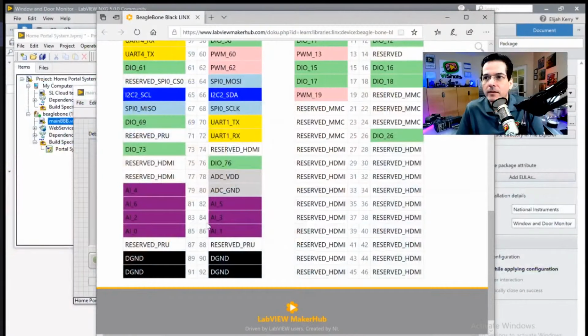It's crazy. Yeah, I will say, I'm confirming there are 7 built-in analog input ports on the BeagleBone, so that is unique for anybody that wants that. There's also I2C. There's clearly a much larger ecosystem around Raspberry Pi. It's far more ubiquitous amongst hobbyists. But from my experience using both with LabVIEW Community Edition, it's roughly a similar experience. There is the one point you brought up about enabling SSH on Raspberry Pi that is just something you've got to be aware of. They updated that in recent distros of Debian as a result of security concerns. But otherwise, the programming experience is largely the same across the 2 targets.